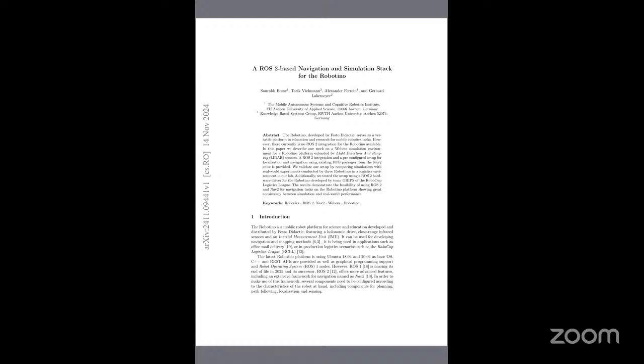Using Navigation 2, they implemented autonomous navigation, and they have compared results between the simulation robot as well as the real robot. Using the ROS2 hardware driver, they have conducted experiments in the real Robotino. And the result was that in both scenarios, the simulation as well as the real robot, the Robotino is showing the same performance.